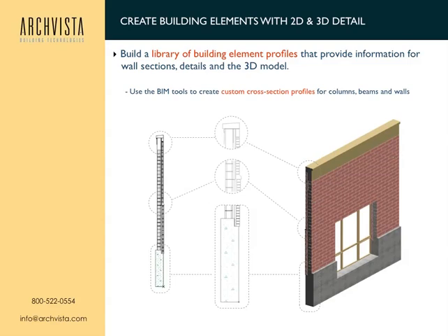So this allows us to quickly create very detailed wall components, slab components, and roof components. And as we draw and extrude them, we can take our section tool or our detail tool and cut sections and details, and pull those into other drawings to begin to further develop the drawings that we're going to need for our construction documents.